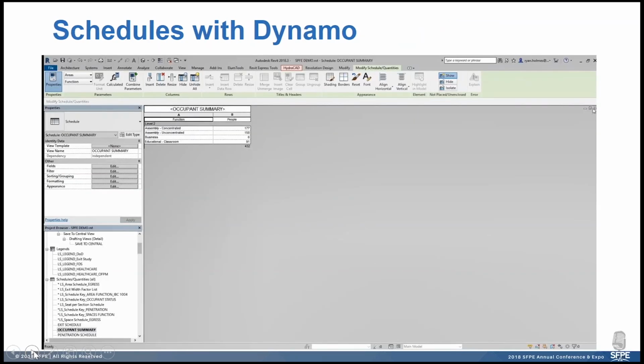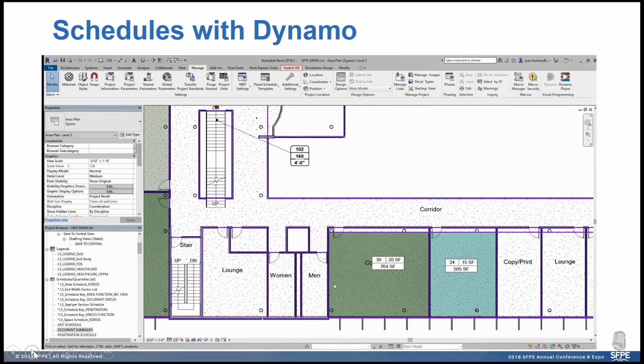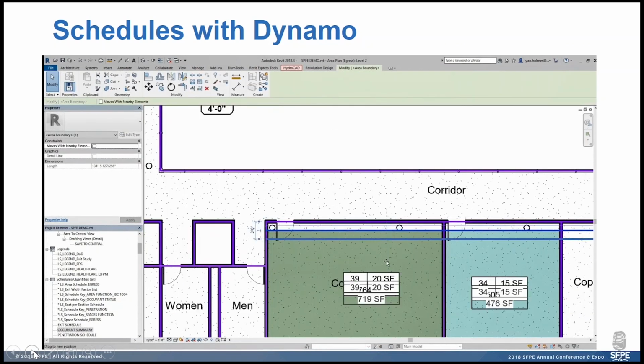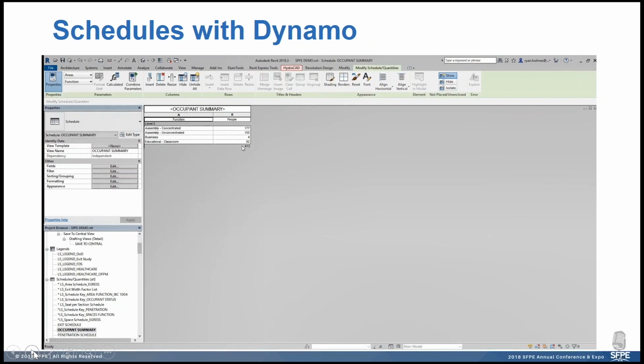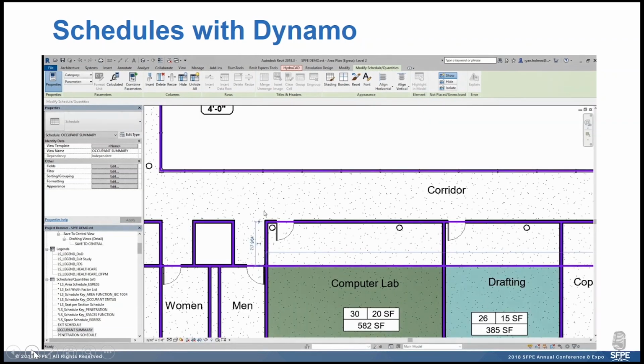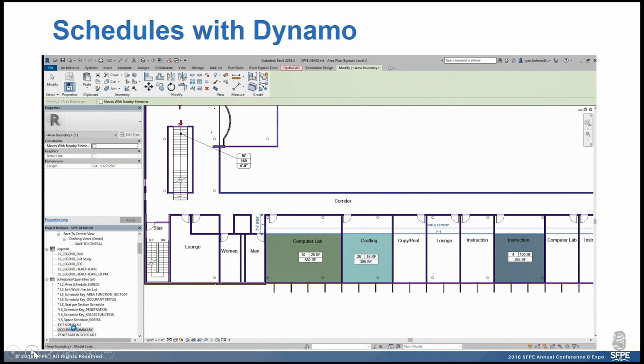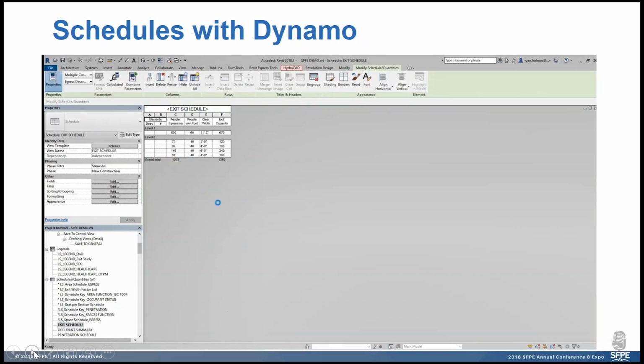One thing that's really cool about Revit is schedules. Granted, I have people in here, but I don't physically have any objects, but I have a number, and I've taught my schedules to look at this number. So the occupants change here, and you can see the total number of people is always accurate. It's always counting who's in this model. And this can be broken out by level, by building type. You can customize your schedules however way you want.